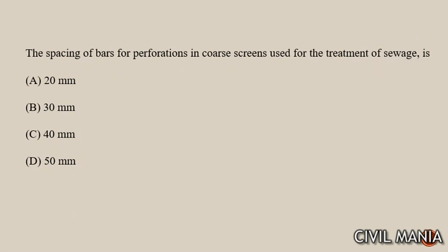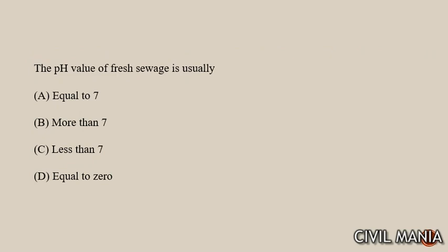mm. The spacing of bars for perforation in coarse screen used for the treatment of sewage, spacing of bars कितना होगा, it will be 50 mm. The pH value of fresh sewage is always more than 7.